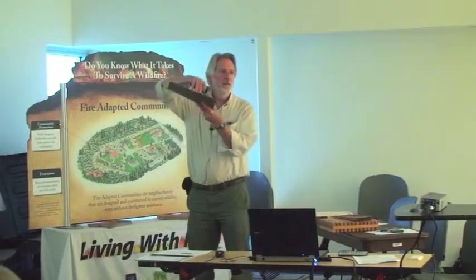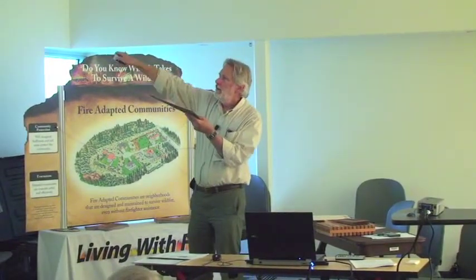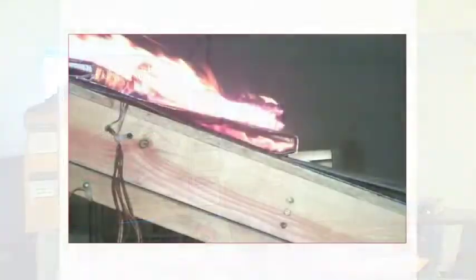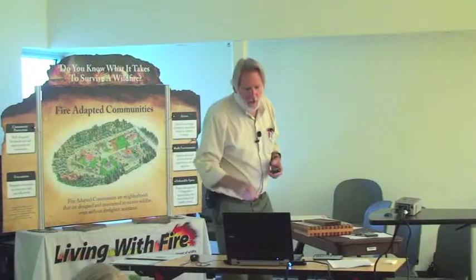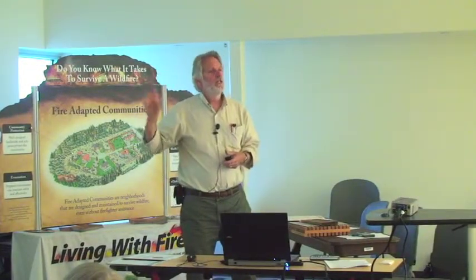So this is an aluminum roof, a picture of an aluminum roof being tested. This is one reason why aluminum roofing isn't really lumped into the same category as steel. Because of the relatively low melting point, the Class A brand, in this case, sits mostly on the thing underneath the roof. What we're seeing here is the Class A brand sitting on top of this cap sheet material. In this construction, it'll pass, but without it, it won't, because the Class A brand sitting on top of it will burn right through the covering. So another example of an assembly-rated roof covering.